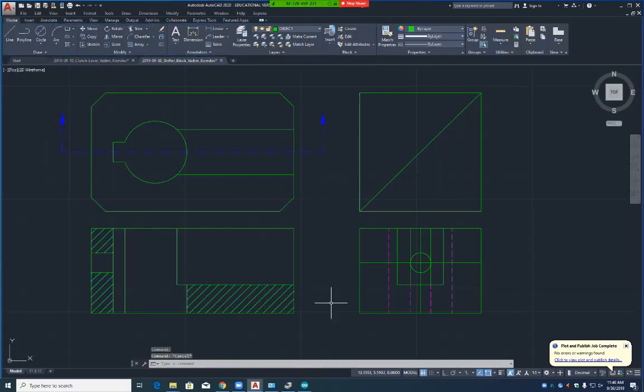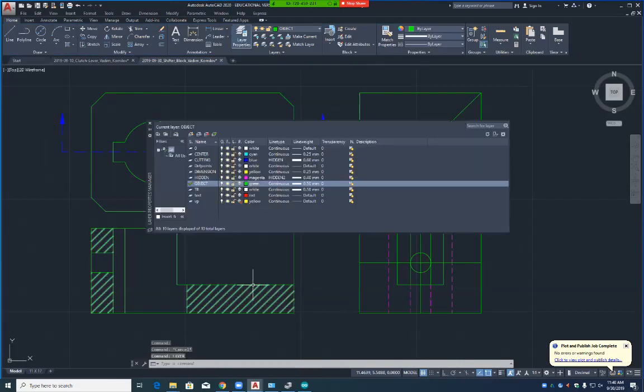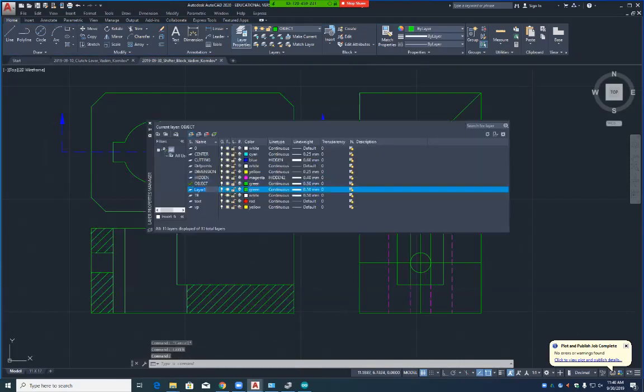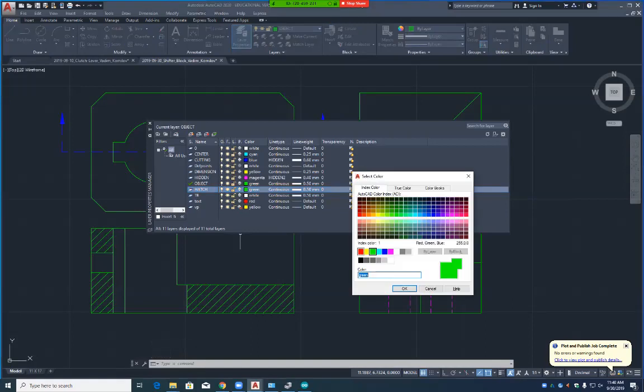Go to that first box right here, and just call it hatch. Did you insert a new layer called hatch? I haven't used red yet, have I? So there's red, so there's the color. We want continuous, but the line weight you want 0.4.